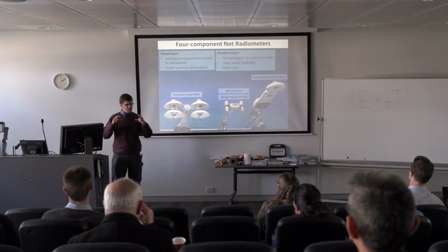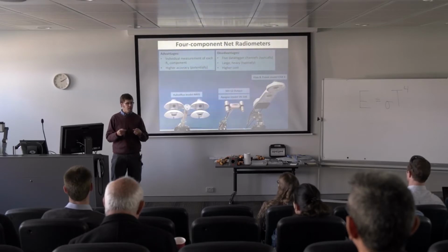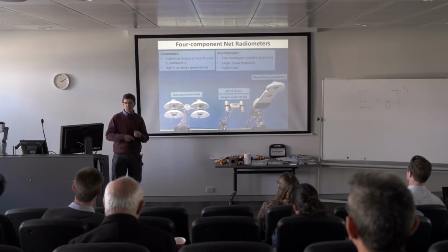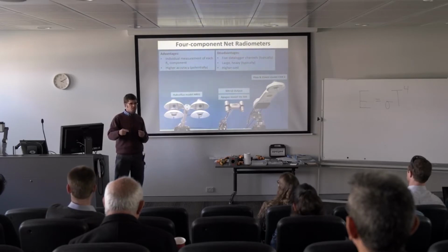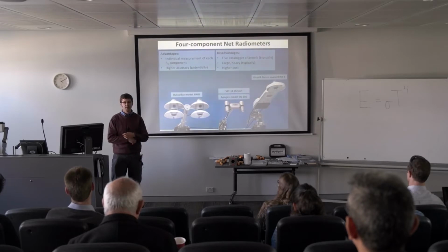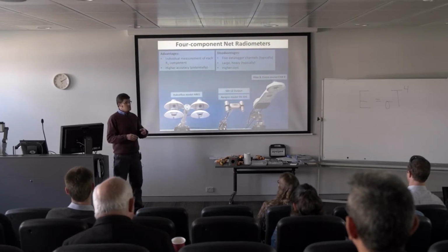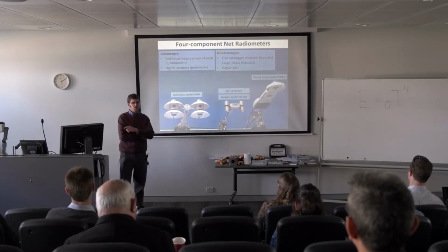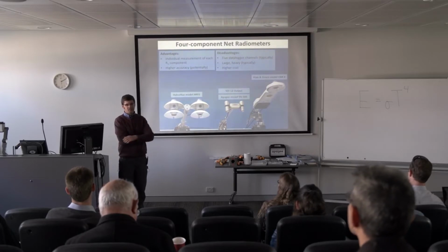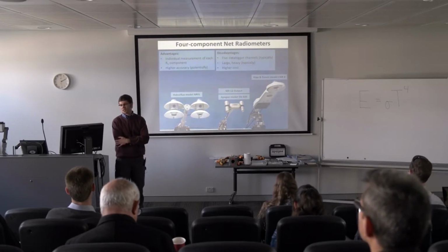All the outputs from the individual radiometers are being measured by the analog to digital converter on that internal circuit board. And then we're just digitizing those signals and outputting an SDI-12 measurement so that you can plug it into one single digital channel on your data logger and not have to tie up all of the analog channels to make the measurement.